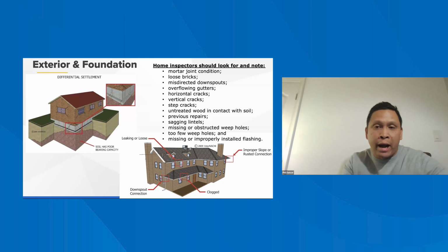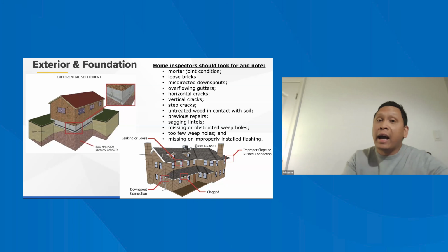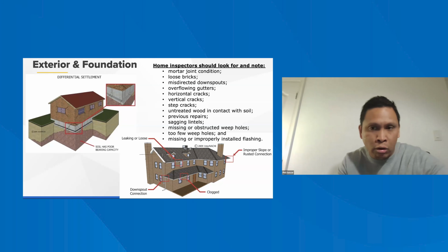So if we were to see a crack, let's say for example, that is less than a quarter of an inch in width, you would probably, without any movement, most people would agree that that is not a structural concern. However, if the crack transitions all the way through the wall, and it's hard to know, but it's important to also put that into your report, then it can allow water to transition into the home, even though this crack is not large, less than a quarter of an inch in width.